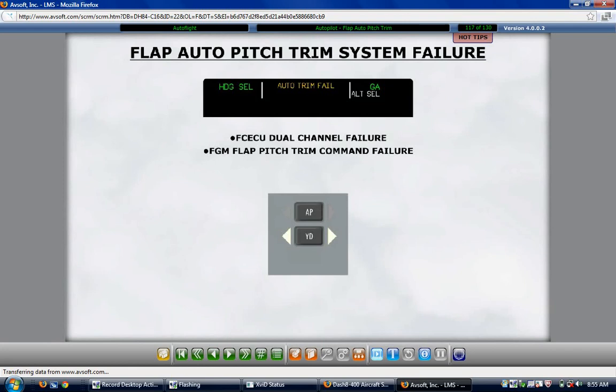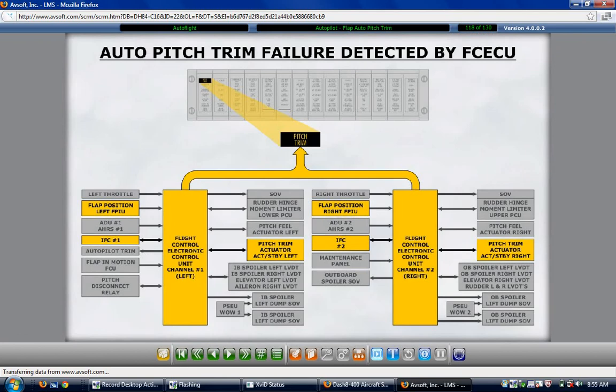During autopilot engagement, each flight guidance module monitors the autopilot roll servo torque. When the servo torque exceeds a certain limit, the flight guidance modules cause a display of an amber mistrim trim left wing down or mistrim trim right wing down to appear on the primary flight display. The roll mistrim message is removed when the roll servo torque is reduced below that limit. The autopilot does not disengage automatically when a roll mistrim occurs. The roll mistrim message indicates to the flight crew that the control wheel is mistrimmed and that there may be a significant control wheel jerk when the autopilot is disengaged.